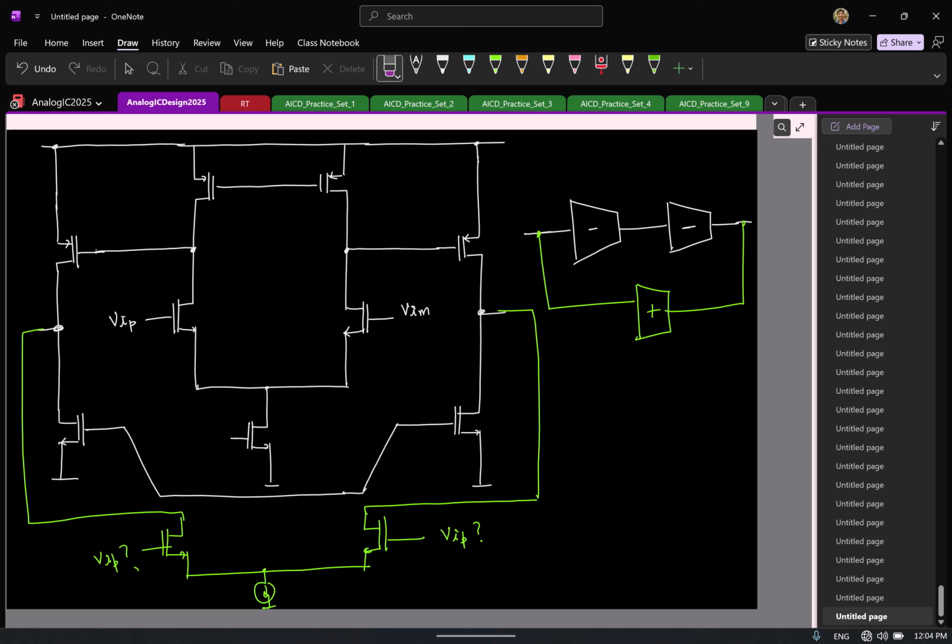Okay, first of all, can I connect it randomly here? Can I toss a coin and randomly put the positive input here, or what should be the considerations I should have in mind? Both parts should have the same current. Same thing you did here. What's the confusion, right? So then how will you find out what is the correct thing to do? Yeah, what you told is correct. Both the currents here should add in the same polarity. How will you find out then what should be the input here?